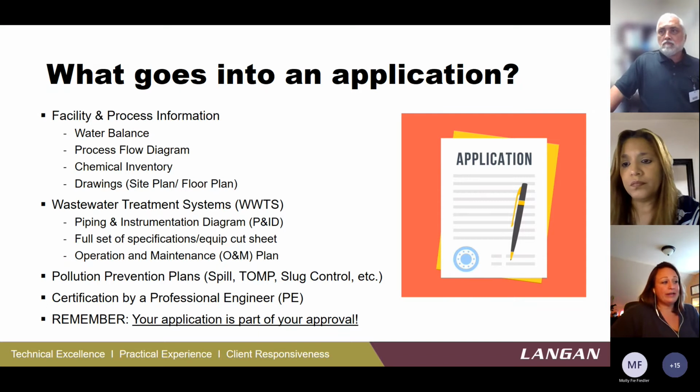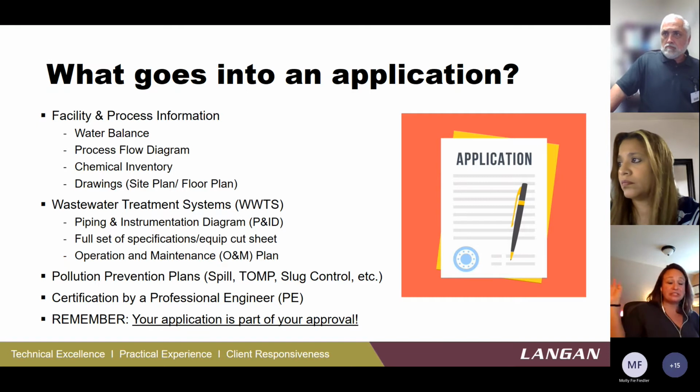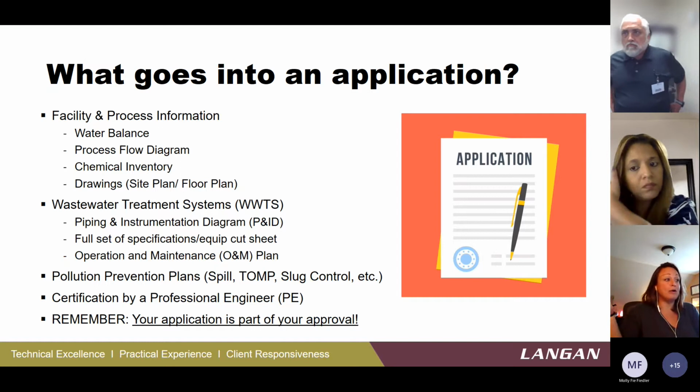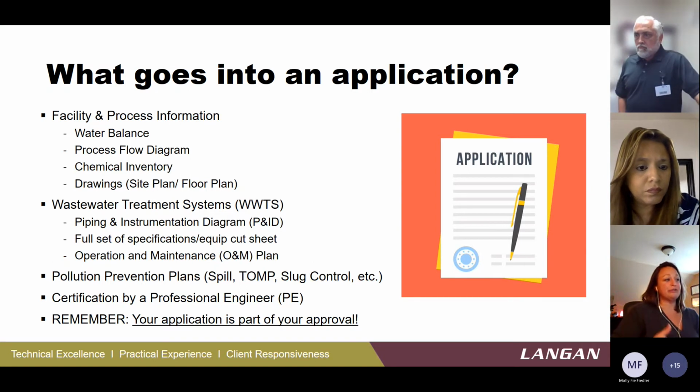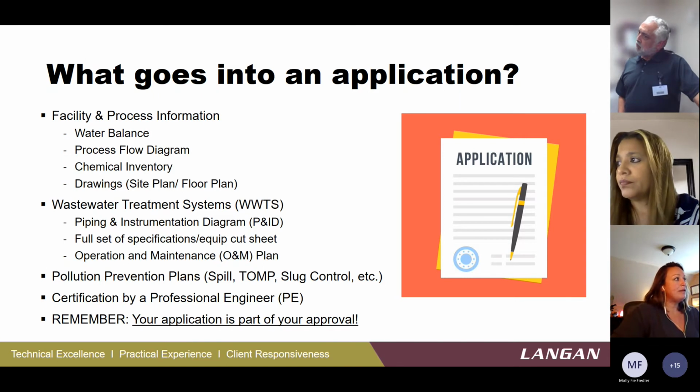A slug control plan, those are for POTWs. So the POTW wants to know that you're not going to send a whole bunch of stuff at once that's going to overcome your treatment system or cause an issue at the POTW. So they generally ask you to develop a plan to ensure that that won't happen. And then most applications do require certification by a professional engineer.